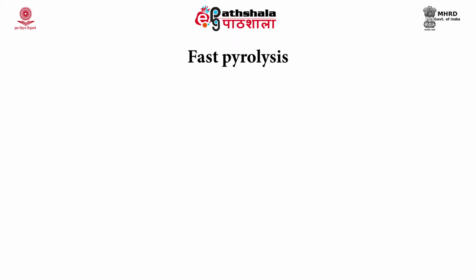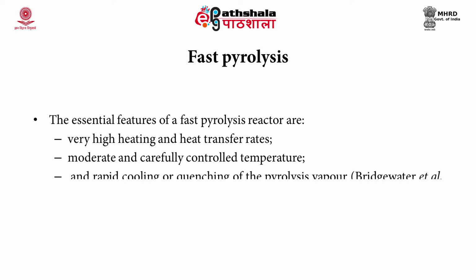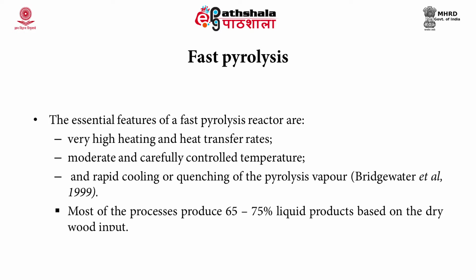Among these, fast pyrolysis is the most efficient one, and most of the research is going on to find the best method of fast pyrolysis. The essential features of a fast pyrolysis reactor are: it should have very high heating and heat transfer rates, moderate and carefully controlled temperature, and rapid cooling and quenching of the pyrolysis vapors.